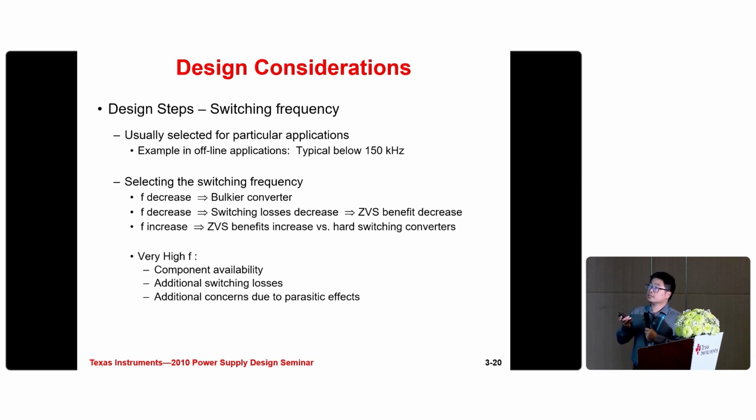And if we want to make the LLC converter operate at a very high frequency, we should be concerned about whether there are suitable components available for the high switching frequency, and we should also pay attention to the additional switching loss and the parasitic effects.